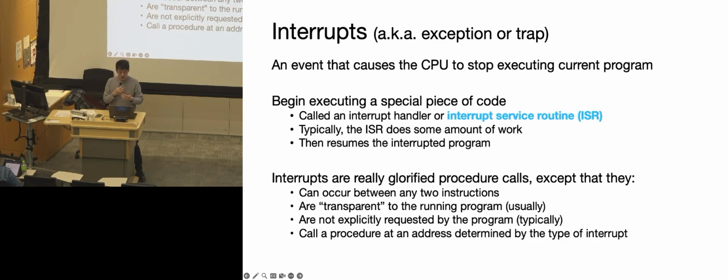And you will probably imagine that normally we try not to do a lot of work within each of the interrupts. Otherwise, you're going to be doing all these ISR routines all the time and the main program also gets stalled. So it's a bit of a trade-off here, but usually an interrupt does something fairly quickly, with a fairly small amount of code to be executed.